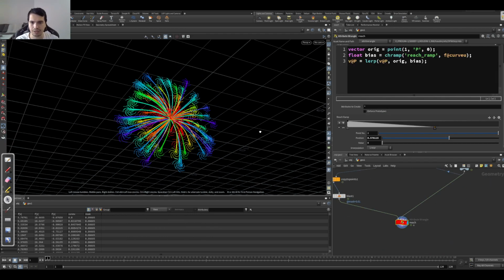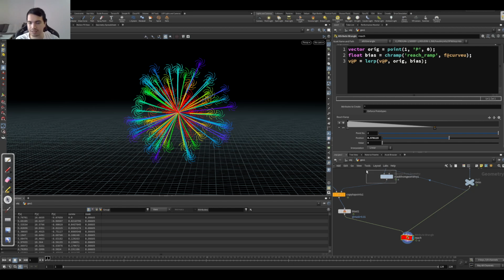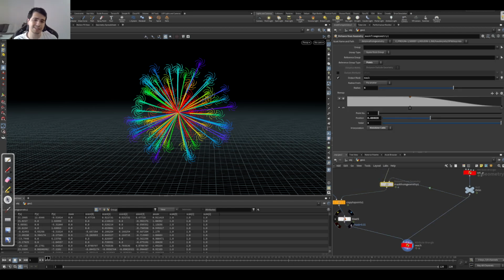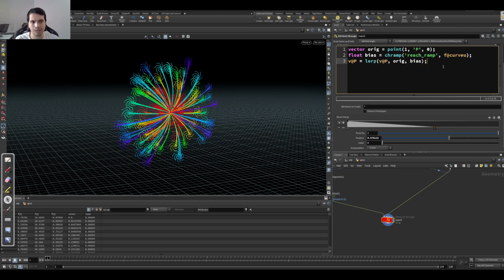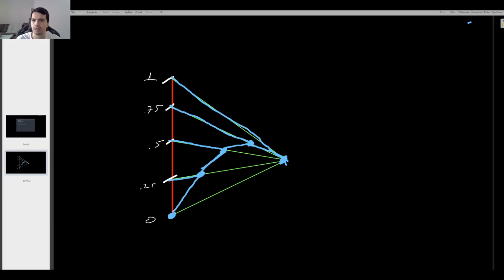Now this is reach. They are all reaching out. I will use this mask attribute to decide how much I'm retracting to the origin. Now how can we do that? If I use it with linear interpolation just like this, it doesn't work. Why doesn't it work? Because right now my origin is here. You see, my positions are here. Let's draw it. You see, this is my foot, right? If I use linear interpolation, this position will try to retract through this path. I don't want it. I want it to go through itself.